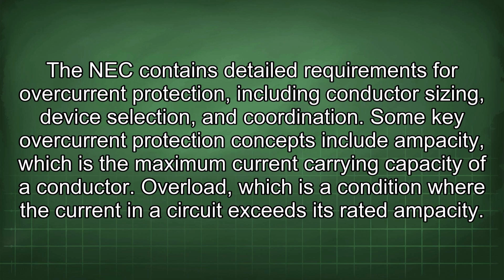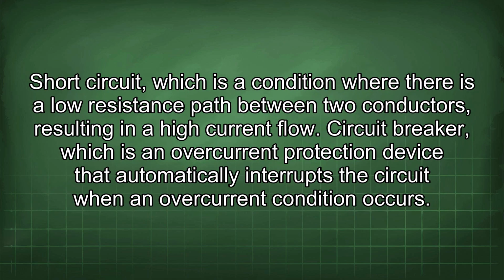Some key overcurrent protection concepts include ampacity, which is the maximum current carrying capacity of a conductor; overload, which is a condition where the current in a circuit exceeds its rated ampacity; short circuit, which is a condition where there is a low resistance path between two conductors, resulting in a high current flow;